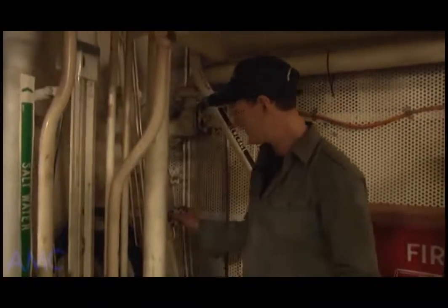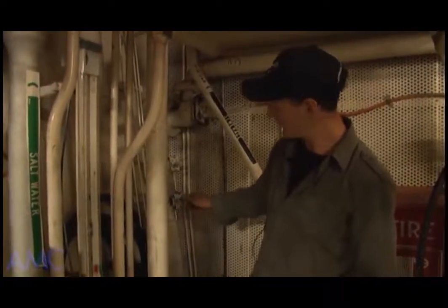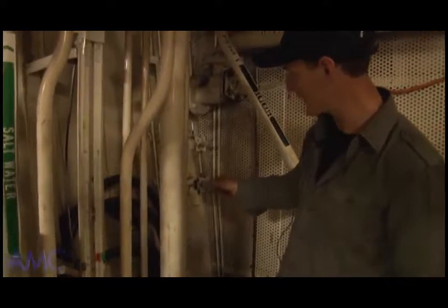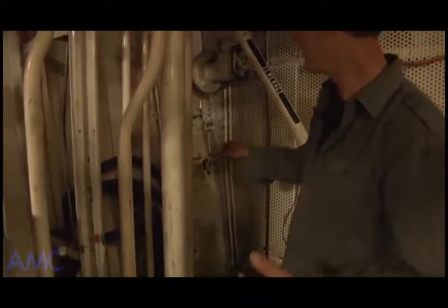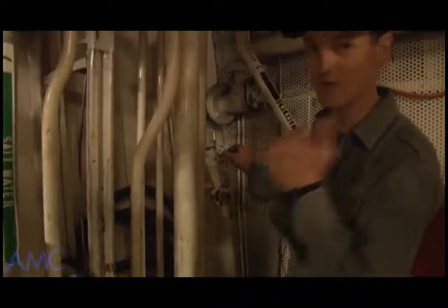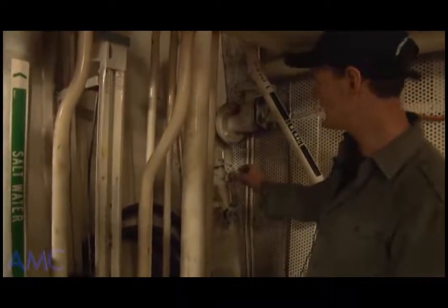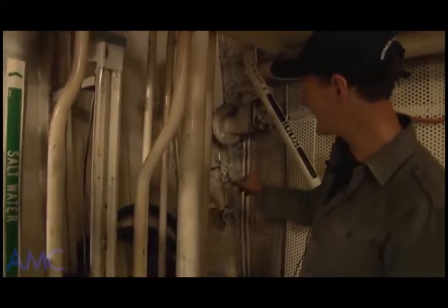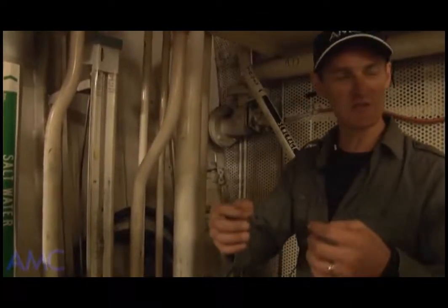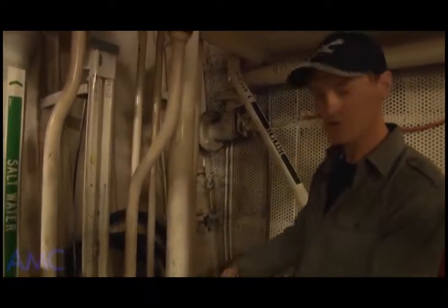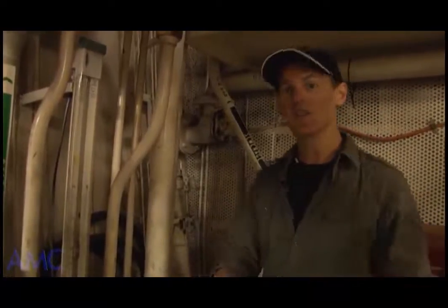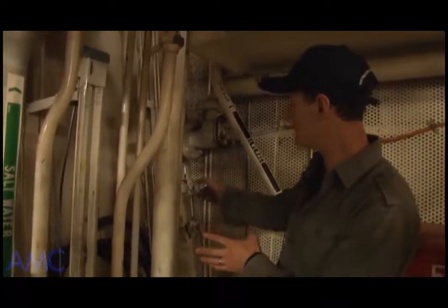So what we have to do is come to this valve setup here and select which tank we want to read, whether it's the port or starboard bunker tank or our day tank. Then we've got this device which helps us calibrate the level that's in there for the tank that we want to read. It's a 4-part process. We start with the zeroing and we wait a period. What it's got to do is use pneumatic air pressure to push all of the fuel in the line back to the tank, and then we wait, we zero it.